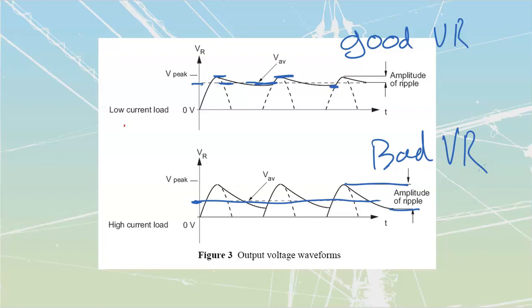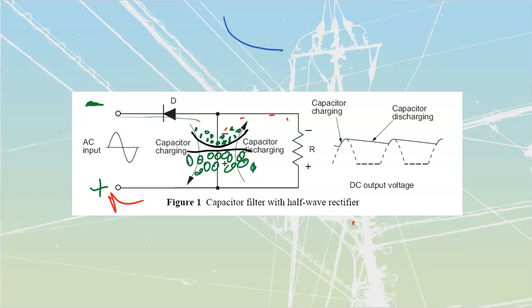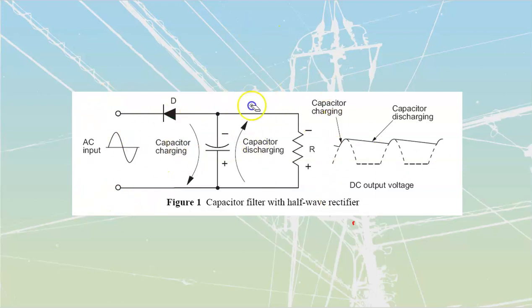The caps that we will utilize inside of these are usually going to be electrolytic capacitors. Electrolytic capacitors are really easy to manufacture. Remember, it's that aluminum oxide that we're building up on them. We covered that at the very beginning of this year. And they're going to be a polarized type of capacitor. We identify which leg is going to be the negative leg because it's going to be the short leg. It would be a negative thing if your leg got chopped off. So we term that as being our negative leg